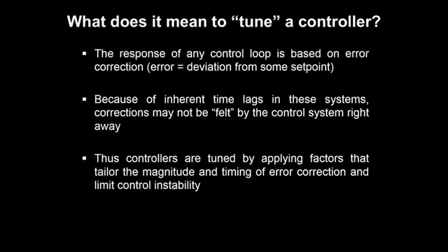You might hear that these controllers or control loops are able to be tuned. What does that mean, and why might we want to tune a PID loop? Well, there are different elements, as we'll see, within a PID loop, and tuning those individually will change the control response that we have. It can make it more robust, faster, or less prone to instability. The reason we need to tune is because each control loop is really specific to the process variables in place and the different feedback lags that we may have. Even though we may see advertised controllers that are factory tuned, we really need to be able to tune the system to the specific application and distribution and infrastructure that it belongs to.